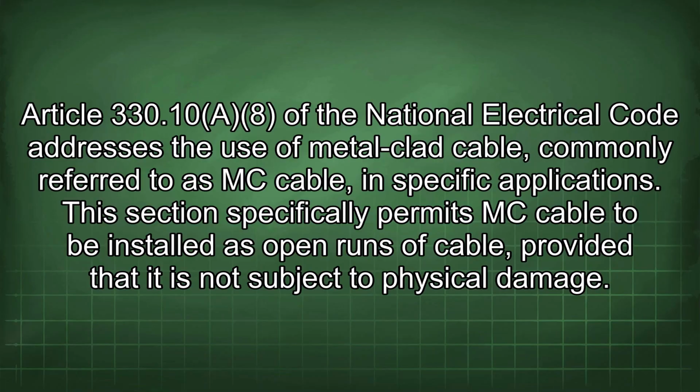Article 330.10(e)(8) of the National Electrical Code addresses the use of metal-clad cable, commonly referred to as MC cable, in specific applications. This section specifically permits MC cable to be installed as open runs of cable provided that it is not subject to physical damage.